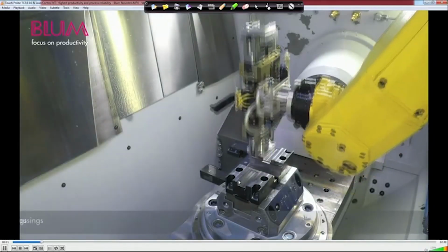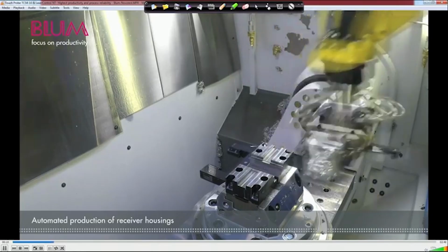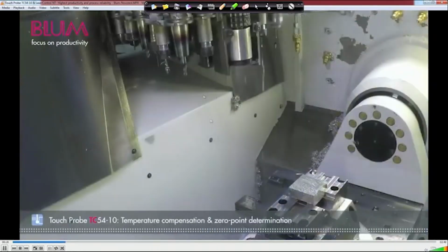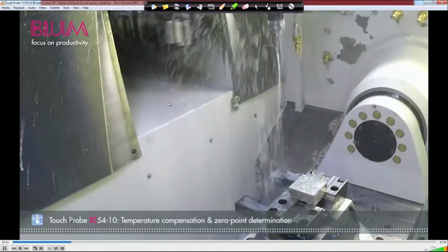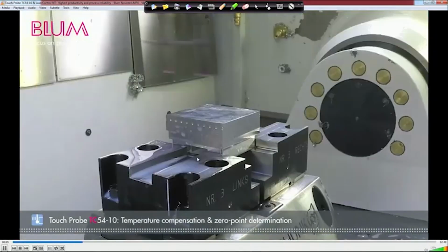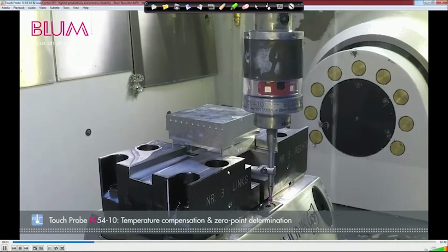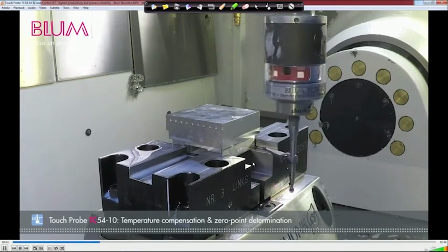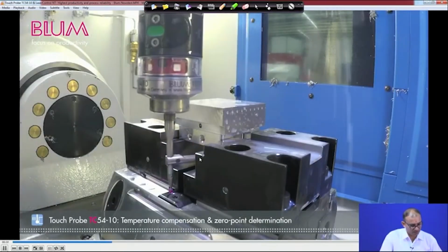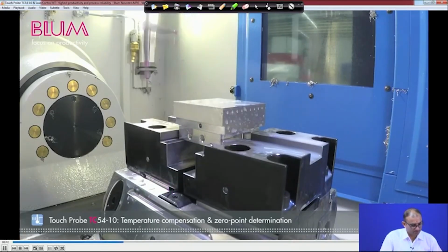Right. So, initially this is the setting of the component where you are putting this part, and this is the cleaning of it. Now, it has cleaned the surface and then you are putting this part, and now there is a touch probe available. So, this is the touch probe by which you are sensing the position, where it is located exactly, whether there is a deviation in the measurement or not. So, by this way you can do all the measurement. This is completely wireless, you do not need any hard wire for measurement. So, this is the workpiece location measurement.